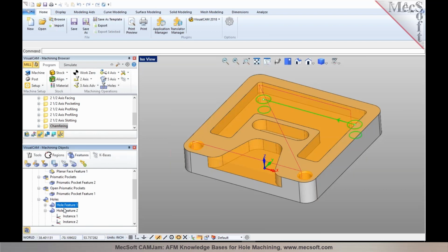types, in the case of hole features, you could have through holes, blind holes, you could have holes with a counter bore, or holes with a chamfer, which could be countersunk holes. Those are identified as a separate category of features, like hole features. In the case of milling features, you typically have either closed pockets or open pockets, and they all can be programmed as a milling feature. That's why we differentiate between holes as a separate feature type versus the milling features.